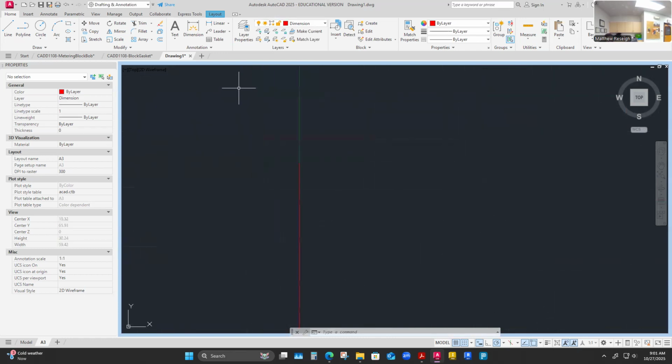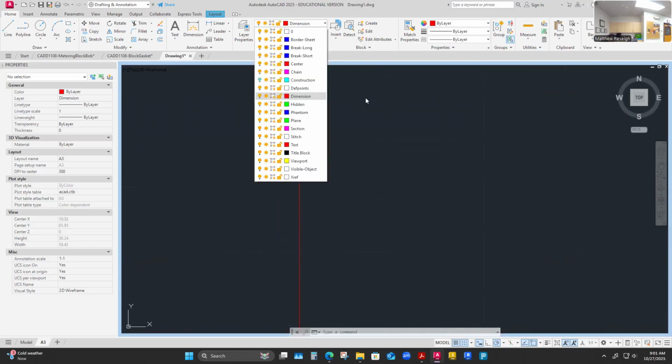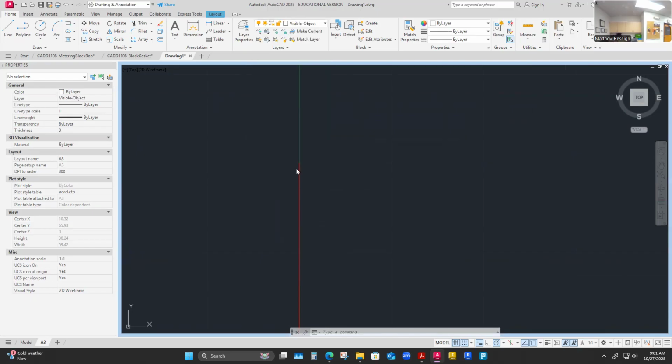If you remember how I made my arrows, I could make those on any layer that was continuous. And I think I chose to make these on a visible object layer. My polyline is my arrow that has a width of point. This is metric, so it still is a double the size arrow. And this is something that's maybe not ASME standard, because I feel like you could probably use a normal size arrow on this too. I'm just using a cutting plane arrow for my axis arrow.